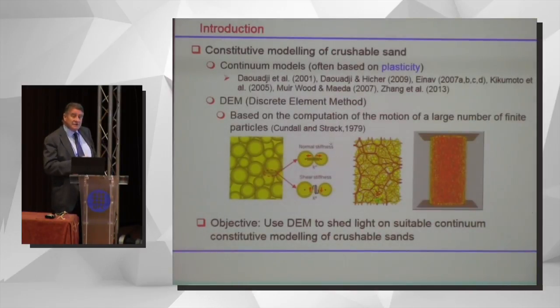So, crushing is an integral part of the constitutive modeling of these materials, which are often based on plasticity. And here there are some references. But sometimes these materials are modeled directly using the discrete element method, which, as you know, is based on the computation of the motion of a large number of finite particles.